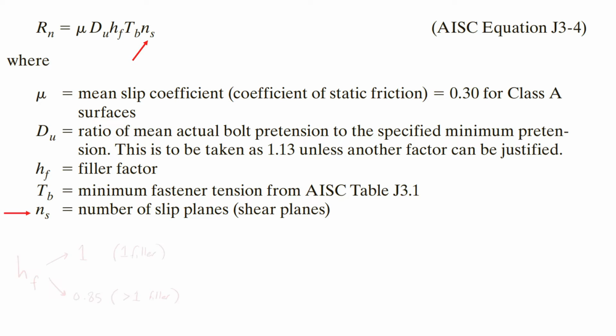The filler factor is equal to 1 when there is one filler layer and equal to 0.85 when there is more than one filler layer between the connecting elements.